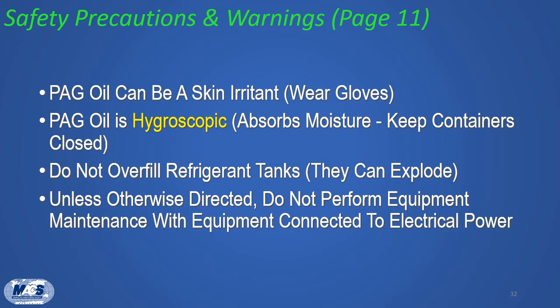Also, always be careful to not overfill refrigerant tanks, particularly when using recovery-only machines. Most incorporate an in-tank sensor that helps protect against overpressurizing the tank, but some don't have that kind of device. Check with the equipment manufacturer's operating guide to learn exactly how to operate your machine and tank.